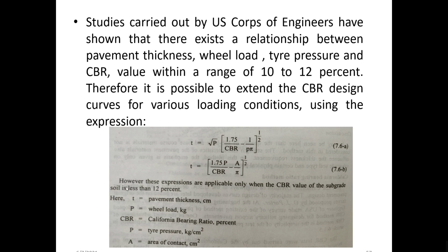So, what does it say? This formula is applicable only for the CBR of the subgrade soil in the range of 10 to 12%. So this is applicable only for soils whose CBR value is lesser than 12%, right? That is a major note that you have to make from the studies carried out by the US Corps of Engineers. Therefore, it is possible to extend the CBR design curves for various loading conditions using the expression. So for different loading conditions, you can extend the CBR curves.